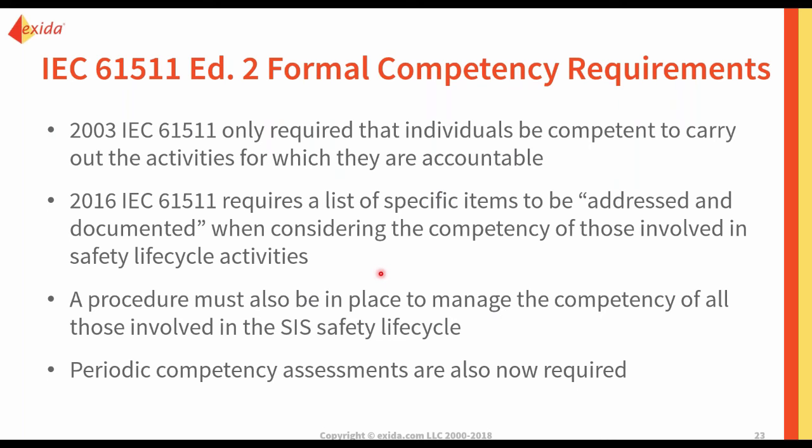So making sure that you have formal requirements for competency and that they're being documented and periodically assessed. And so really with that, a procedure must now be in place to manage the competency of all those involved in the SIS safety life cycle, and a periodic assessment of that competency is also now required.